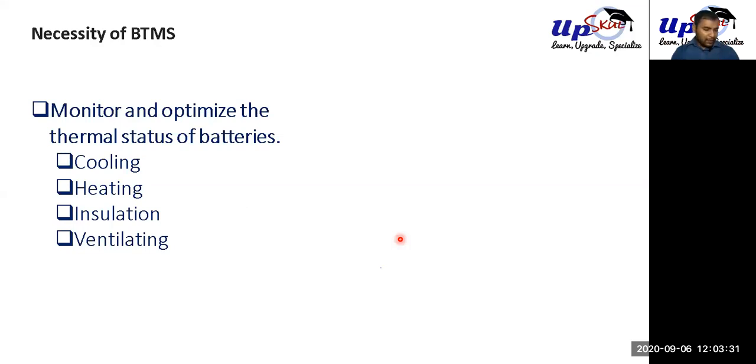Ventilation is important just in case toxic gases start to build up inside the battery. There should be a place for them to get out, right? Otherwise, the gases will eventually blast the battery. It will be violent.